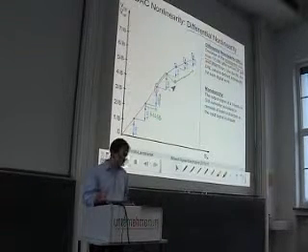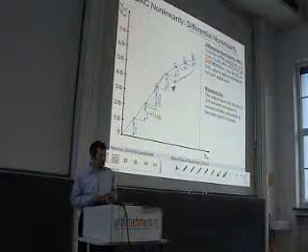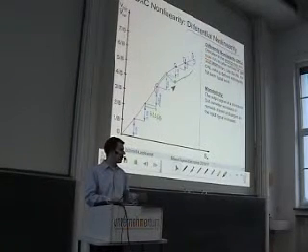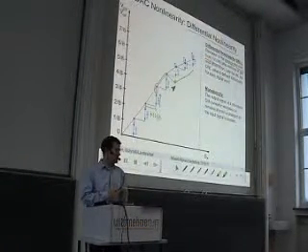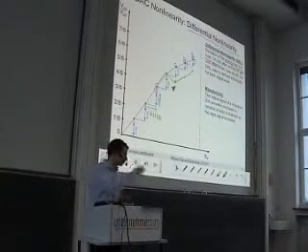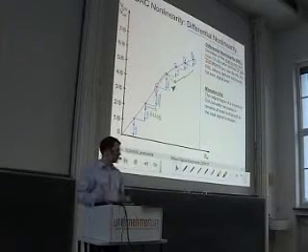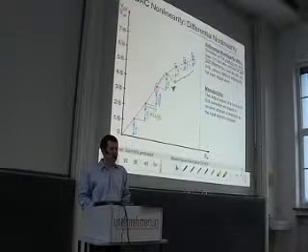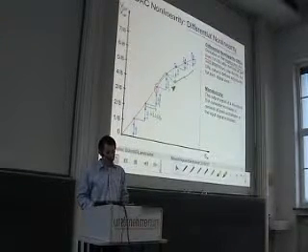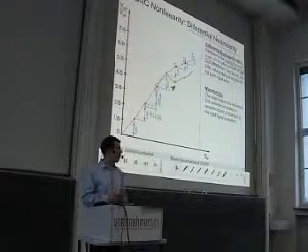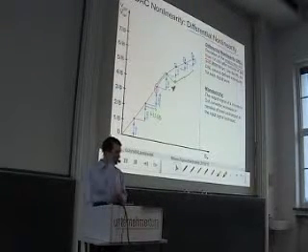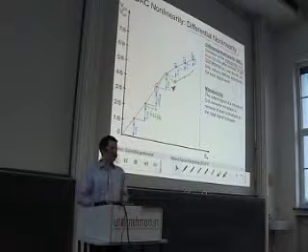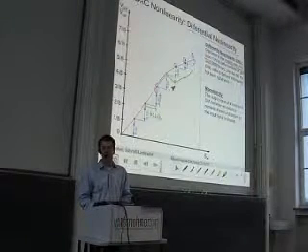One thing that should be mentioned for all accuracy or linearity figures: if one value is given in a data sheet, for instance, integral non-linearity, one value, then this is the largest one. It is better and carries more information if you give a complete curve, which means that you define for each point the non-linearity value.